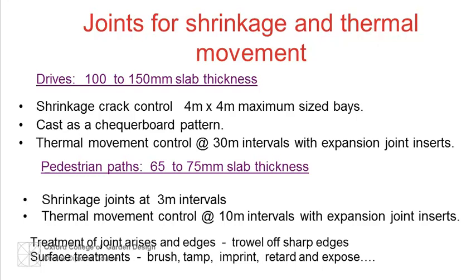Alternatively, a deep groove can be cut in the green concrete surface by an abrasive wheel, or a V shape of polythene sheet wrapped under a metal bar can be tamped into the wet concrete to leave the polythene embedded in the surface. These methods encourage the inevitable shrinkage cracks to appear in a controlled rather than a random way.